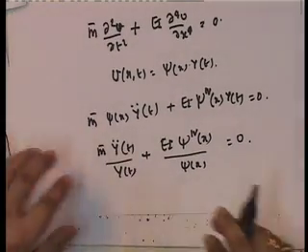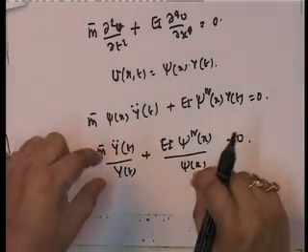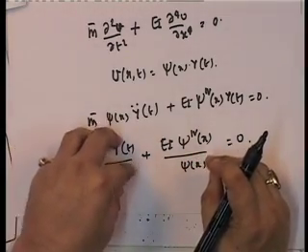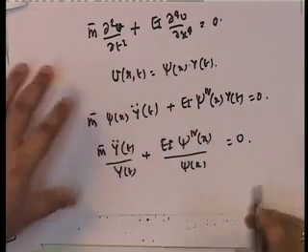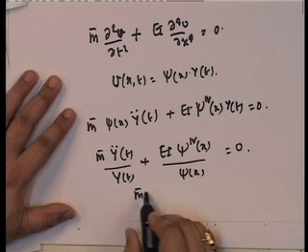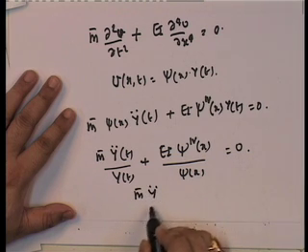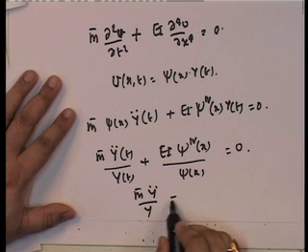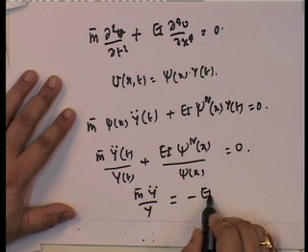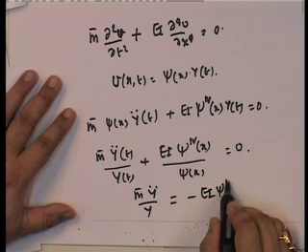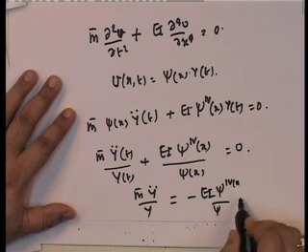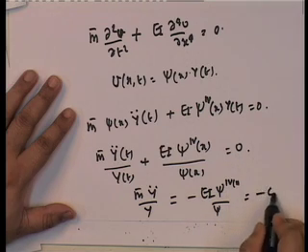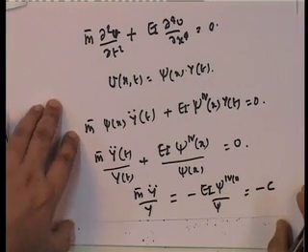So, what we get is the only way, again you see, that a function which is only a function of t and a function of x can be equal is if they are both constant. And so, if I write this in this fashion, minus E I xi fourth upon xi is equal to minus c. So, then I get the following equations.